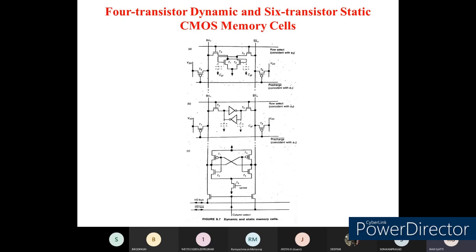So you can see here the gate capacitances C1 and C2 which have been connected to the bit and bit bar lines, whereas the transistors T1, T2, T3 have been connected over these bit terminals, whereas we are going to connect the VDD values by using 2 PMOS transistors, that is T5 and T6.